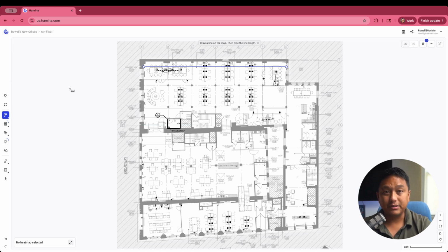But now I'm dealing with a building, and I want all of these floor plans to be aligned, and the alignment will help us when it comes to seeing the propagation between floors. I don't know if you've been in an environment where you can actually see the signal of an AP on the floor above you or the floor below you. And in this model, we'll want to try to predict what that signal strength will look like coming from the APs on the adjacent floors.